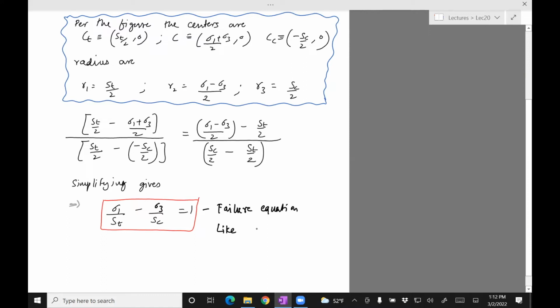Remember we did tau max equals Sy divided by 2, and sigma prime equals Sy. So this is for the MSS, and this is for distortion energy. So we have these expressions for those theories. This is a similar expression for DCM, or Ductile Coulomb-Mohr Theory. Okay, so I'll post this derivation, but I don't think it's very essential, so I just don't want to spend time deriving things.